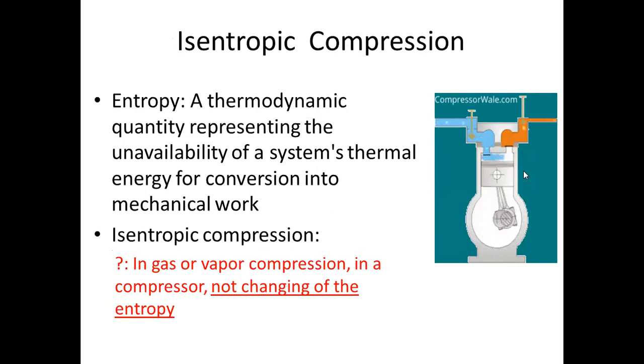So suction and compression, pumping to a high pressure side, maybe even in the refrigerant compressors, low pressure low temperature gas from the suction, compressed to a higher level of pressure and sent into the condenser.